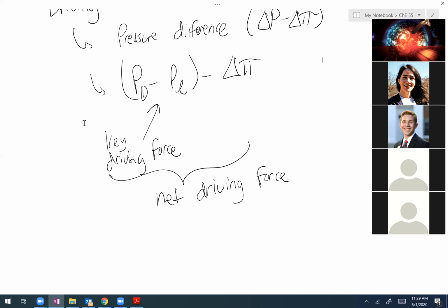When we looked at, in brief, Knudsen diffusion and things like that, concentration is going to be a bigger factor in those circumstances. But we use pressure primarily because that's typically what's being applied to enact the separation, right? And keeping in mind the key driving force is the easiest approximation for our chemical potential difference, which is what's driving the separation to begin with. And so that's why in most of these processes, pressure is used, because we can easily control it, we can easily monitor it, and we can relate it to what we get in terms of performance through these membranes.